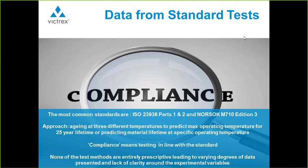They are both very similar in their approach, in as much as mechanical test pieces are aged at least 3 temperatures in an environment, and the data is used both to demonstrate on a comparative basis how well the material resists chemical attack, but also to provide an estimate of a maximum operating temperature, which would provide a 25-year material lifetime.